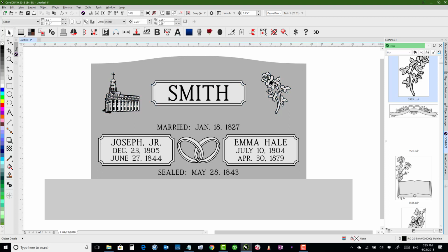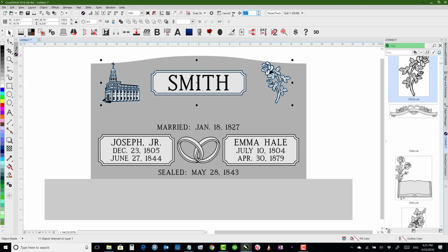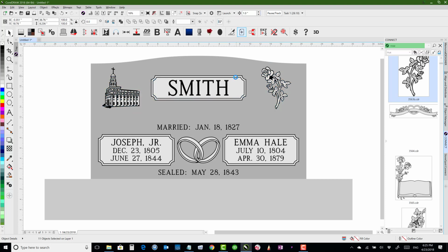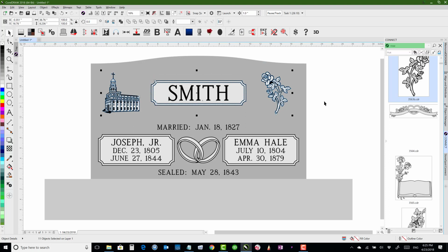Normally, if I click off here, the nudge is actually set right here when you have nothing selected. But I moved it onto the top bar here because a lot of times when I have something selected, I want to do a custom nudge. So let's just say I want to go up by 2 inches. I'll swipe it, hit 2, and then I'll push up. So that's kind of why I moved it up there, so that I've got quick access to being able to do that.